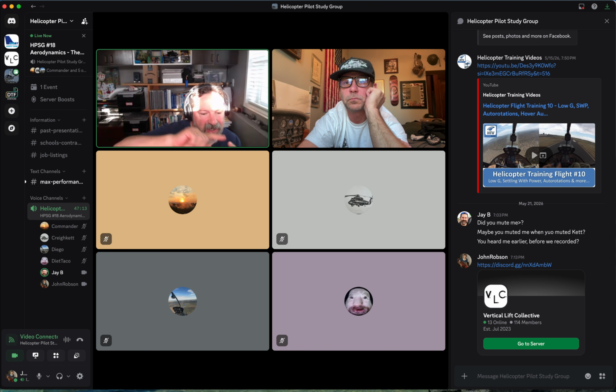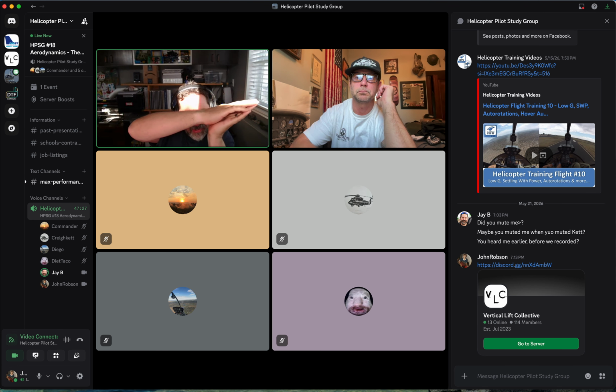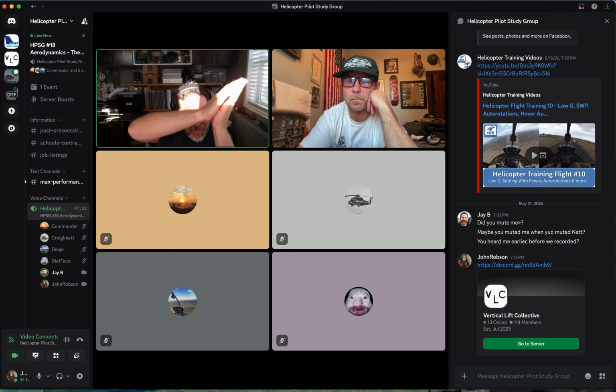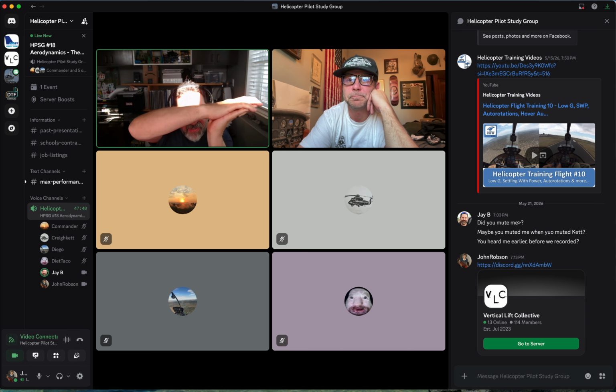My understanding is they went symmetrical because it's cheaper and easier to make. But also when the angle of attack changes on a symmetrical airfoil, like the Robinson, the center of pressure doesn't really move very much. That means there's not much control feedback force. But if you create an asymmetrical blade, then you get more lift efficiency, but you get these feedback forces.